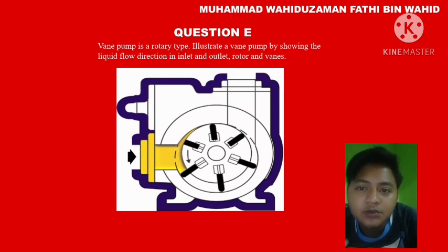As the rotor rotates and fluid enters the pump, centrifugal force and hydraulic pressure push the vanes to the wall of the housing. The tight seal among the vanes, rotor, cam, and side plate is the key to the good suction characteristic common to the vane pumping principle.